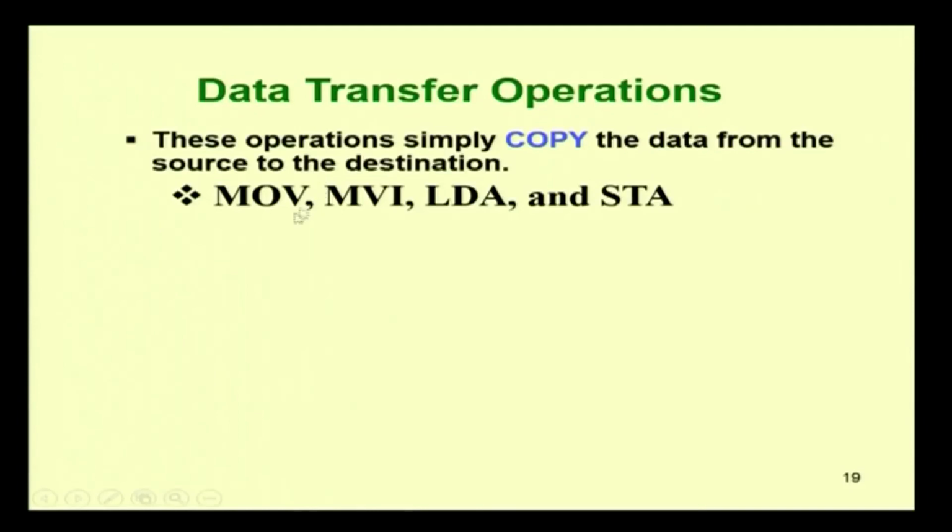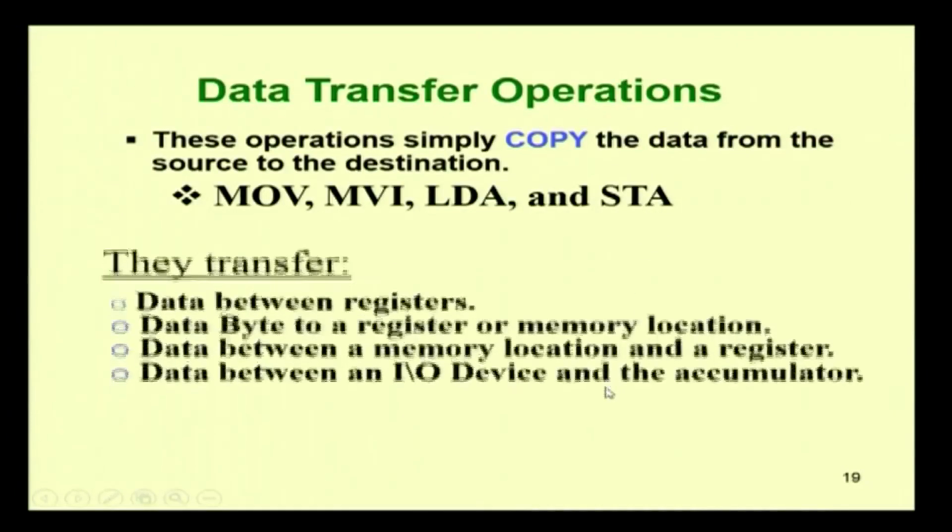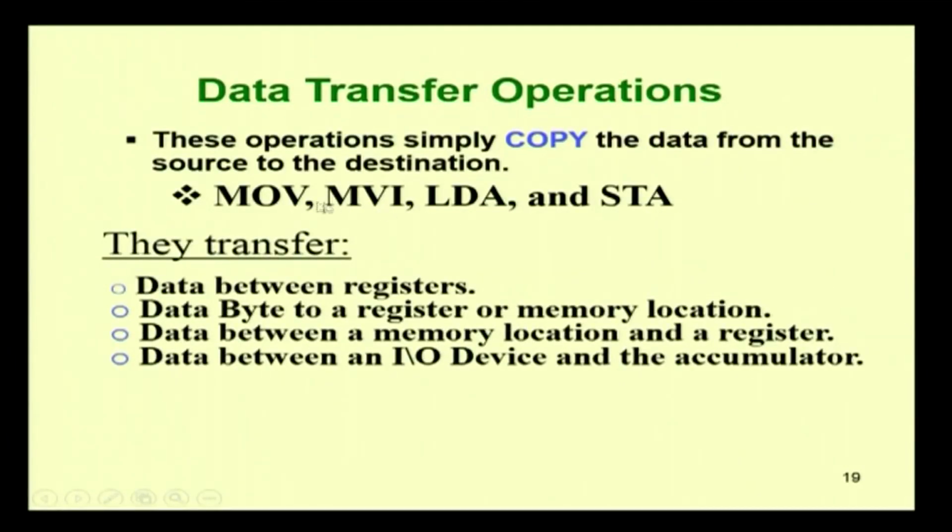Intel has introduced this type of notation, which is called mnemonic. MOV means moving data, MVI means move immediate, LDA means loading the accumulator, where A means accumulator, and then storing, using STA, like that. These are some of the opcodes for data transfer operations.